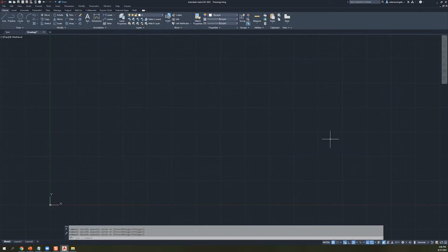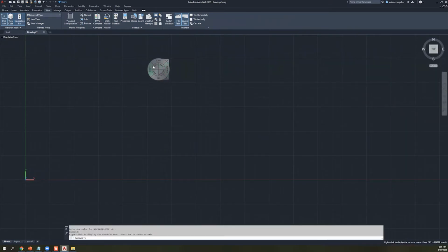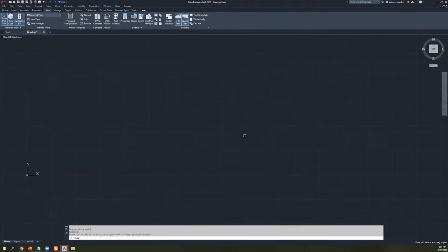Okay. So let's just talk about some of the other useful mouse commands and operations that you could do here in AutoCAD, right? AutoCAD's great, and you have a bunch of different view options over here. And I'm about to get rid of this view bar myself, but it is good to note some of the different commands that are available over here. The first one obviously brings back the view cube, which, absolute classic. That's cool. This next option over here gives you this weird heads up view thing. I don't use it that often, but it's there if you want it. You can manually access the pan command from this button as well with a little hand on it, right?